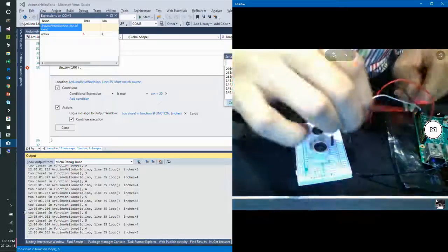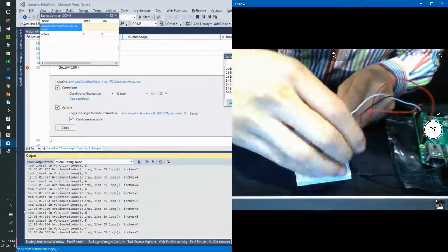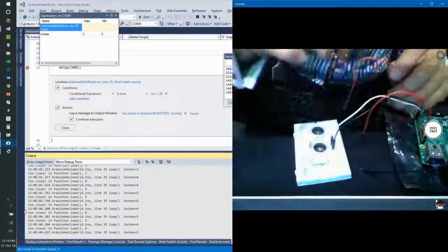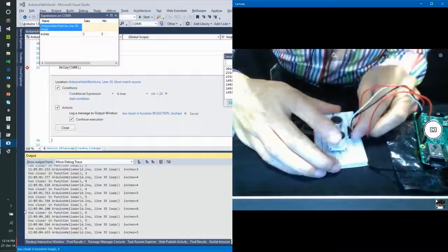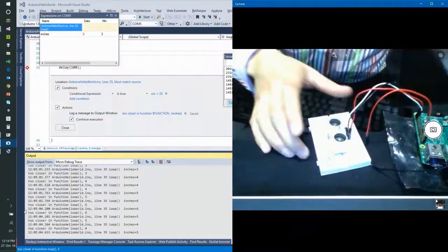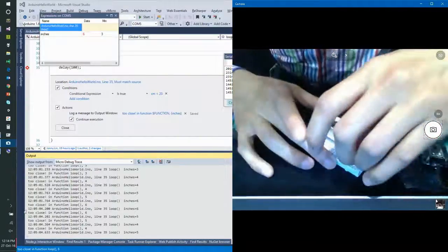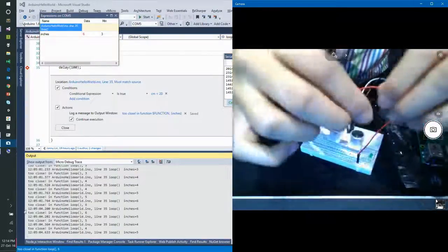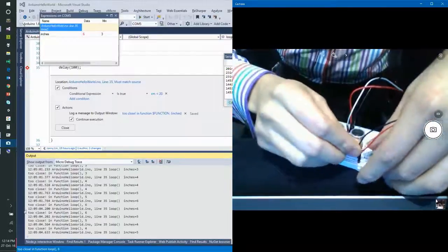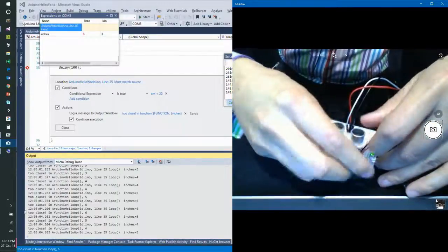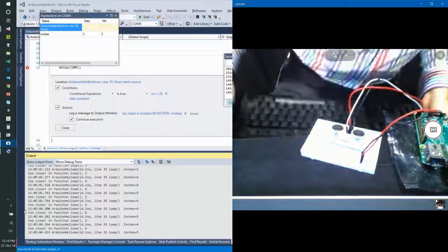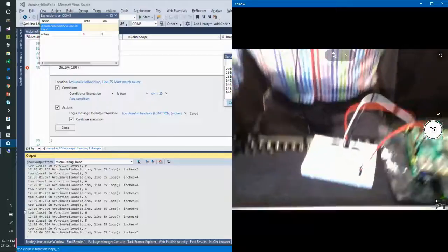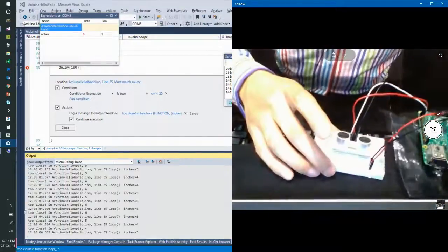For the record, you are not supposed to do this because the sensor runs on 5 volts. And what I'm doing here is I'm hoping the Raspberry Pi's diode will be able to take the blunt for me and it doesn't die. And also for the record, black is ground, red is power. So if you ever get asked to defuse a bomb, try the red one first, I guess. Don't quote me on that.